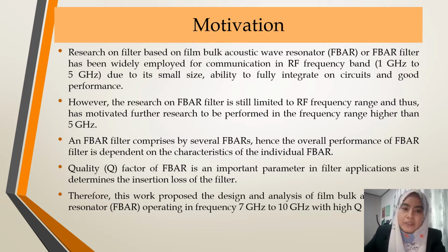An FBAR filter is comprised of several FBARs, hence the overall performance of the FBAR filter is dependent on the characteristic of the individual FBAR. Quality factor of FBAR is an important parameter in filter applications as it determines the insertion loss of the filter. Therefore, this work proposed the design and analysis of film bulk acoustic wave resonator operating in frequency 7 GHz to 10 GHz with high quality factor.